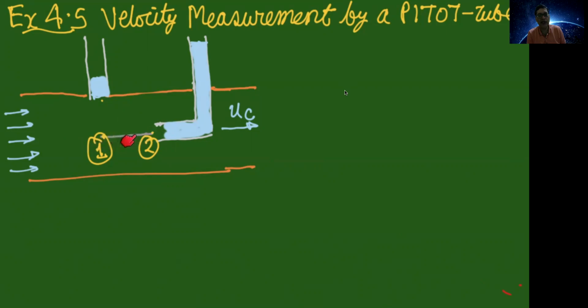So when the kinetic energy is reducing, then the flow energy corresponding to pressure should increase. So here, the pitot tube measures a pressure which corresponds to static pressure plus dynamic pressure, which corresponds to the pressure that is generated when you decelerate a fluid particle from certain velocity by an isentropic process.